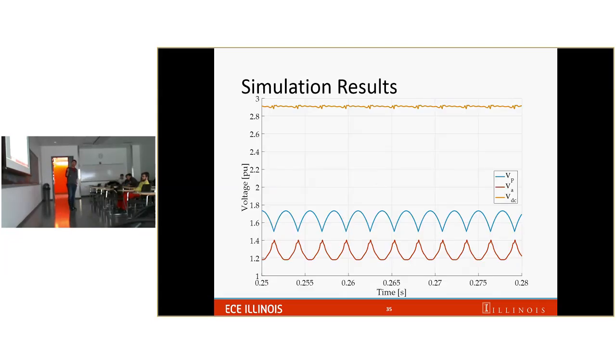However, I have achieved something to conceptually show the feasibility of this. If you see here, the blue line is the diode ripple sequence, and the orange line, but it looks red, it's okay, is the voltage synthesized by the active rectifier, and then we add the two together. The yellow line is the DC bus voltage. Ideally, it has to be flat, but we always have difficulty matching when it suddenly changes here.